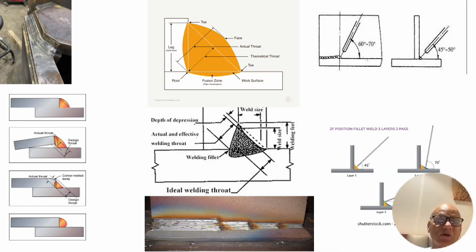And if we are not going to give the fillet, we have to be very, very careful in directing, and we may go from 45 degrees to 70 degrees to avoid this corner joint or corner melting. Otherwise it will be a defect. And if we do too much of vertical 70 degrees, there is a chance that we may have a lack of fusion on the horizontal plate or the second plate, and that may create a problem in the weld. It will be a defect.